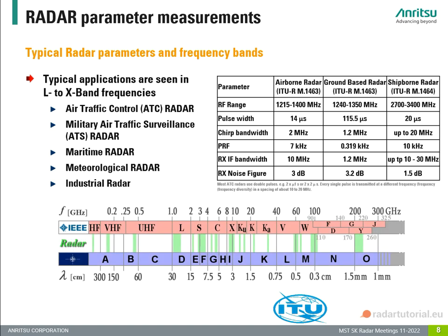But be aware, if you enter into discussions about the radar frequency bands, first agree if you follow the IEEE recommendations or the NATO radar band designations. Usually, if we talk about E-band, we might think about 60 to 90 gigahertz on the background of test and measurement, because we do have the waveguide designation in mind, whereby NATO defines the E-band to be at 15 gigahertz.